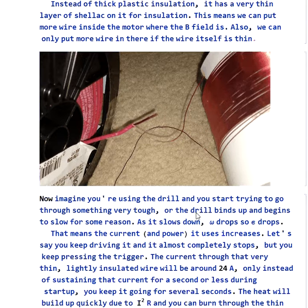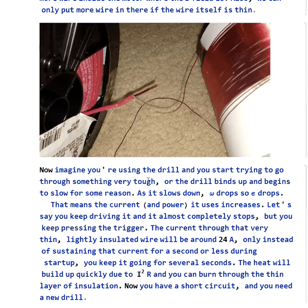Now let's go back to using the drill, and let's say you're trying to drill through something very tough, or the drill binds up and starts to slow down. When it slows down, omega drops. When omega drops, the back EMF drops. That means the current and the power it uses is increasing. So you don't pay any attention to that. You keep squeezing the trigger.